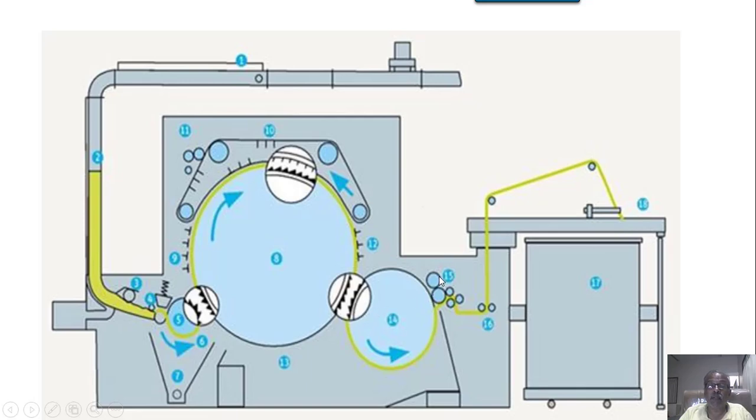Then further the condensing system and stripping, and then the material is taken to the auto doffing type can, because you can see the cascading wheels here at the bottom of the can. Once the can becomes full, it will be doffed, and in place of that a fresh empty can will be inserted here. So that's what we had seen earlier about the importance of the feeding zone and various things which are taking place overall in the modern carding machine. So let's move ahead.